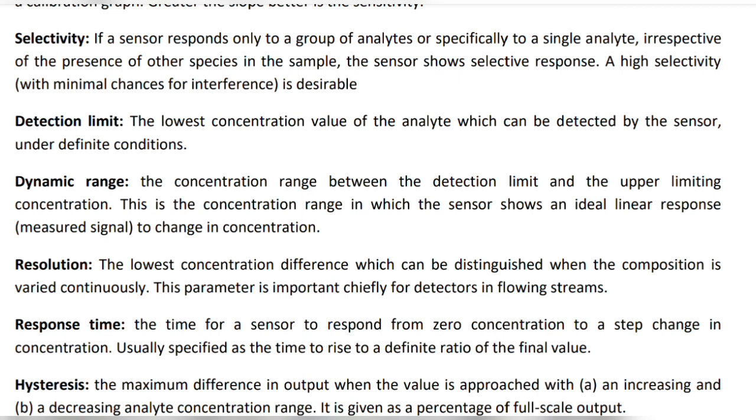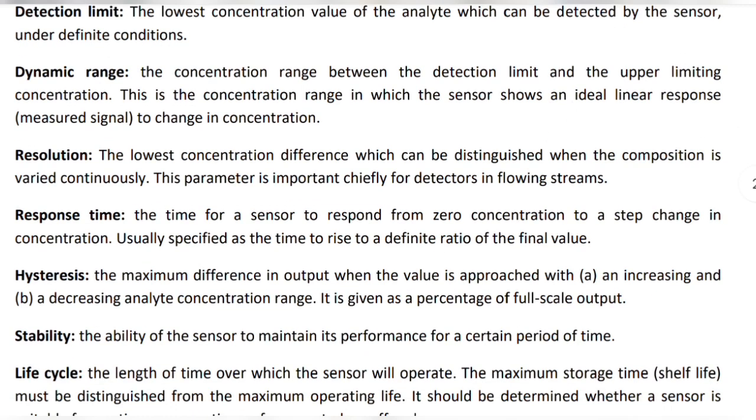which is called the resolution. Then response time means the time required to respond from zero concentration to a step change in concentration. If it varies from one concentration to a second concentration, what is the time required to respond? This is called the response time.